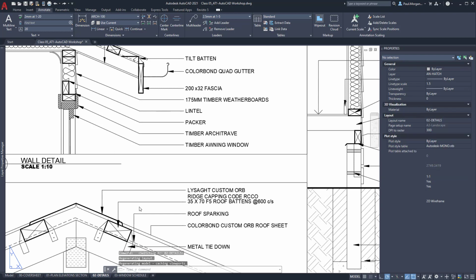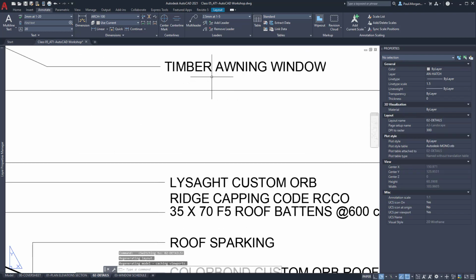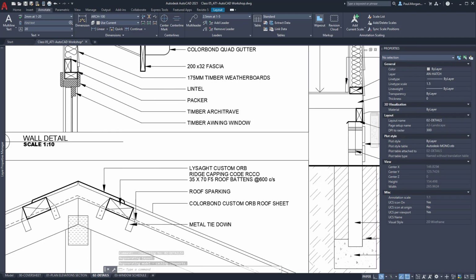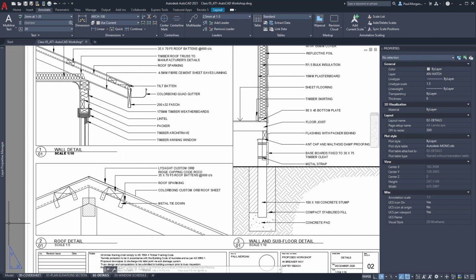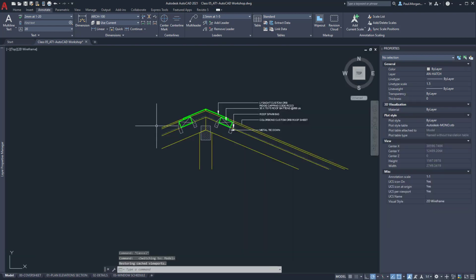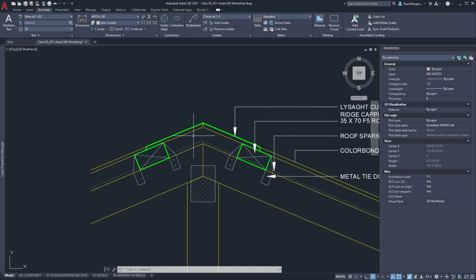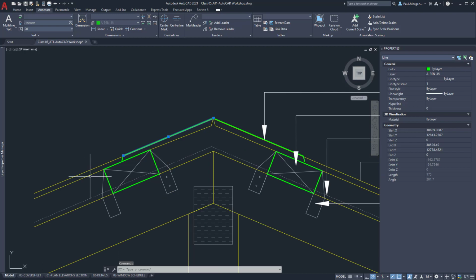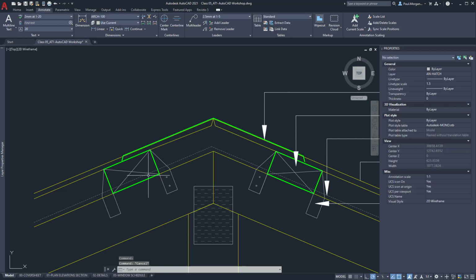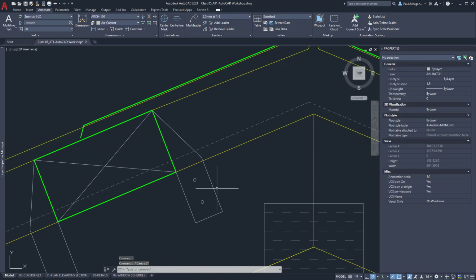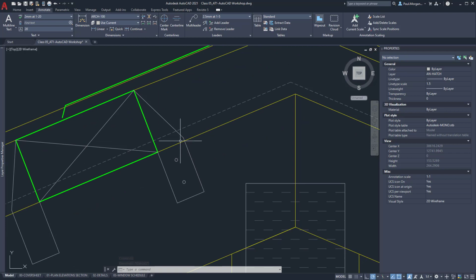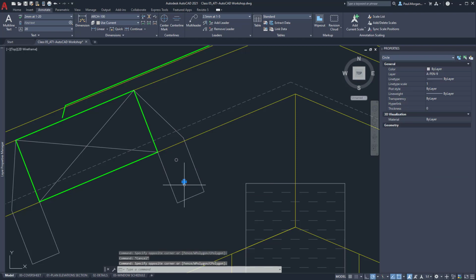Yep, okay. The text between here and here should be the same size. That's important to remember. A couple of other little tips that I can leave you with as you go through the detailing process. The roof cap, the sheet roof cap, is simply just a line, which is a pen drawn at 0.35. The nails in the rafter clamps are simply just pen line weight 0.9 with a couple of circles that mimic something that looks like a nail.